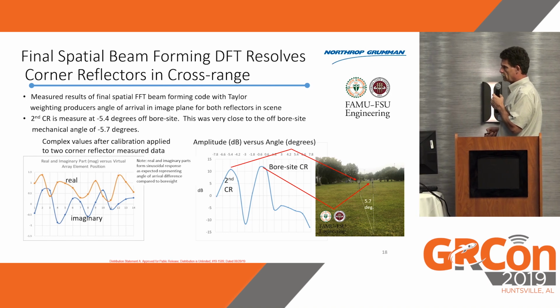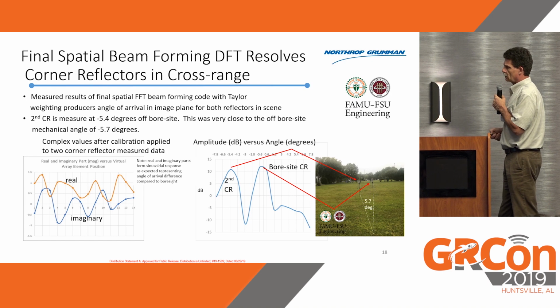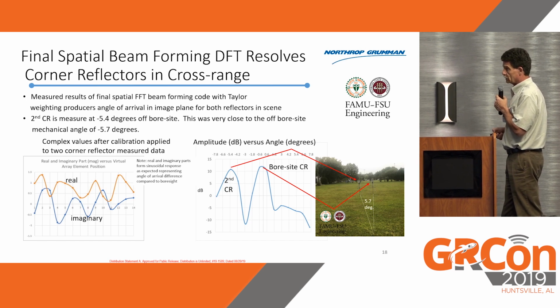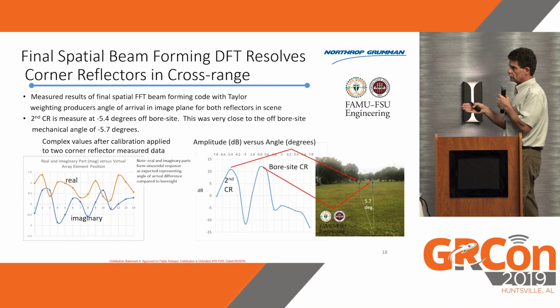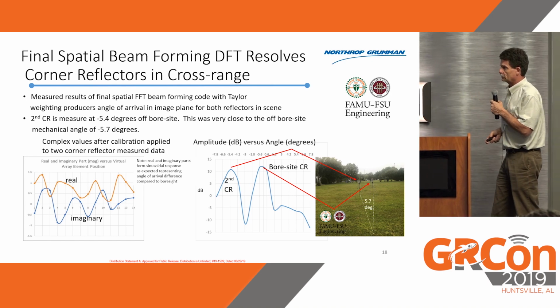So you're using the Fourier transform to decompose this into angle of arrival of the energy, because each scatterer at each angle is going to give you a different sinusoid response in the IQ domain, and the Fourier transform will decompose this into the different frequencies, which corresponds to different angles of arrival for the scattered energy in the scene.